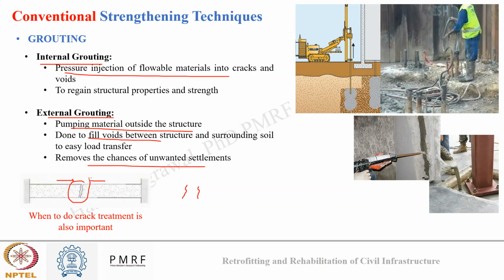Okay, so this will expand. So what will happen? My crack width will decrease. Okay, so this was my crack width. It will come to a very small quantity. Okay, now if I am grouting the material inside this crack, when the winter will come, it will again contract. Okay, when it will contract, it will exert tension on this grout material in between, and there can be an additional crack near the existing crack that may occur.